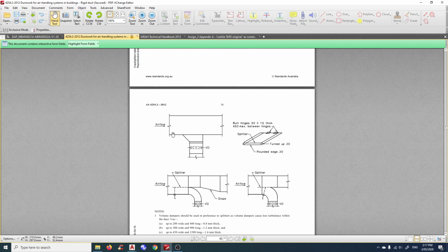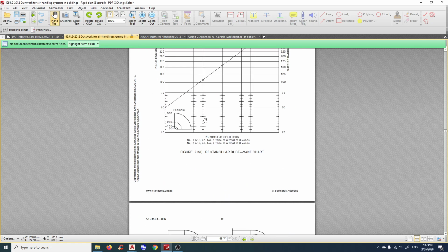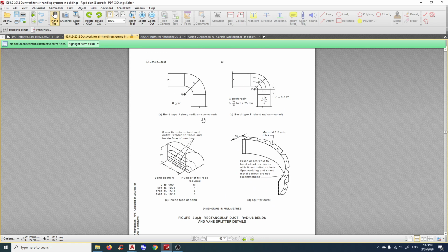Nowadays with a plasma cutter, you can make the duct any shape you like. The key of manufacturing is to make it standard, with as little waste as possible, which means use a standard duct. So that's the key of manufacturing. Try to avoid a weird duct if you can, and that will avoid the waste.